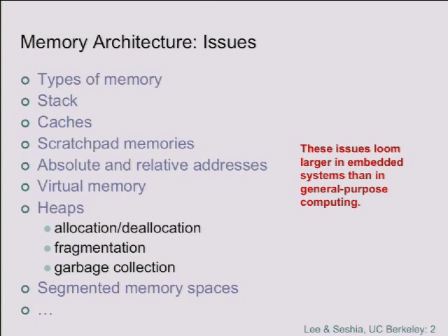The way a dynamic RAM works is that it stores a bit on a charge of a capacitance, and it actually lasts only a few milliseconds. Kind of disturbing that this machine here has 4 gigabytes of memory, and if you cut power to it, within about 30 milliseconds, it will have forgotten everything. So it has to refresh every one of those 4 gigabytes every few tens of milliseconds, or it forgets everything, right? It's not only volatile, it's very volatile. It's kind of transient, right?